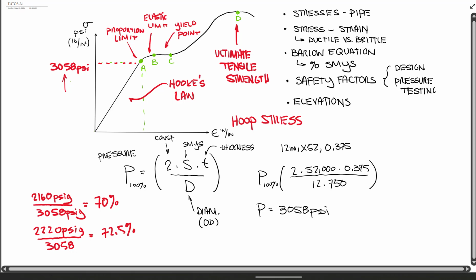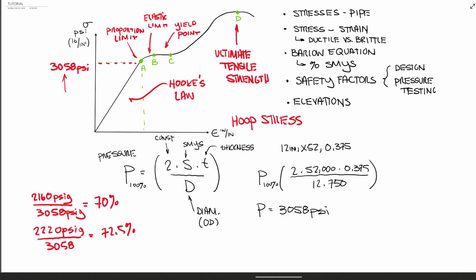Now, you'll see in some specifications, like welding specifications, they'll say, hey, you're allowed to have a girth weld this close to a threadolet weld as long as it's less than 20% SMYS. So as long as you know the 100% value of any piping you're looking at, you would just take your part of the whole. Okay, so how would we figure that out?